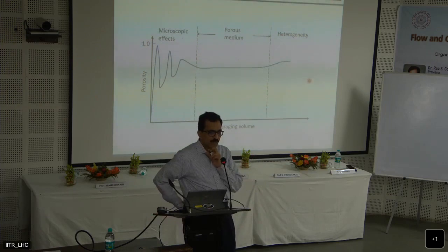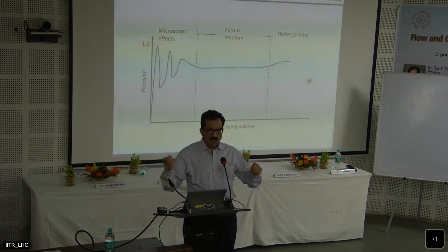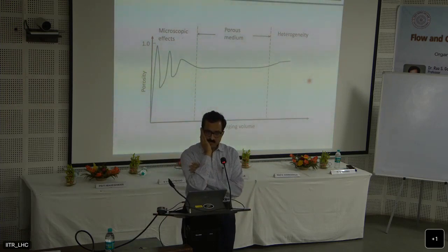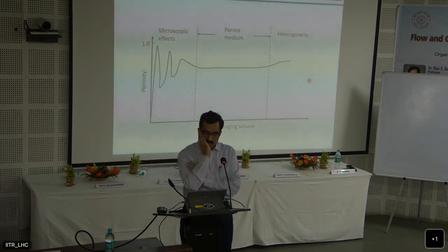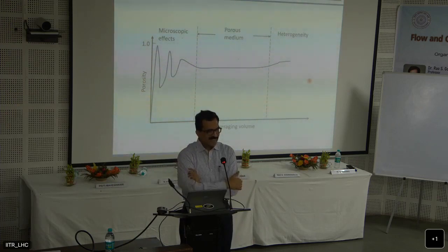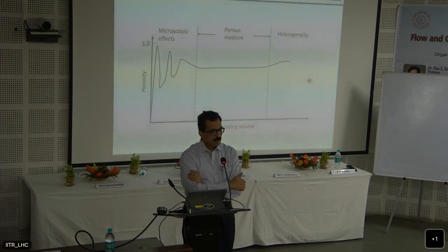So effective porosity: you can determine the total porosity. You can drive out all the water from all pores. You can do that. For the same soil, if you conduct an experiment with a conservative tracer and see the breakthrough curve of the tracer, you can get an assessment of what the effective porosity is, or the active porosity.